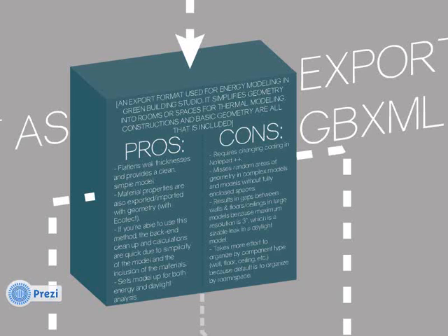With that being said, material properties are exported to some extent in both the SketchUp and the Ecotect method. What's nice is this also sets up the model for energy analysis. So if you're exporting it as the GBXML to get to daylight analysis, you'll have the option to do energy analysis as well. That's really what this file type was mainly built for, exporting out to energy simulation.